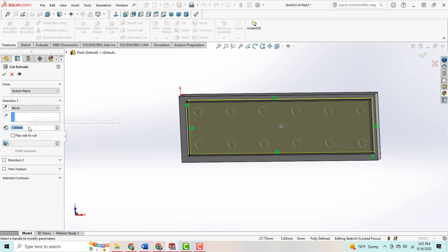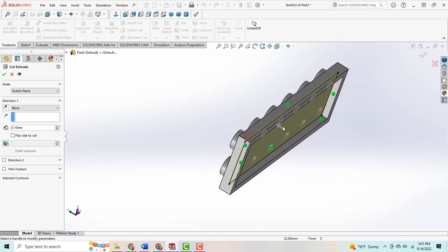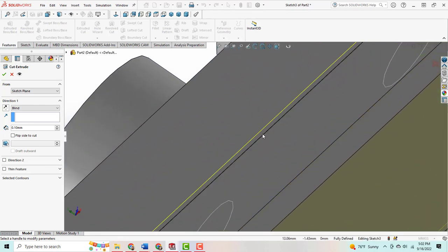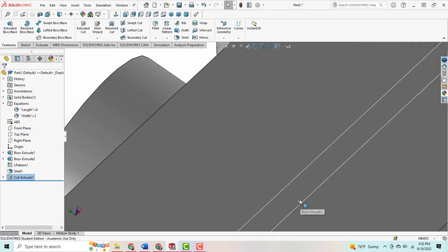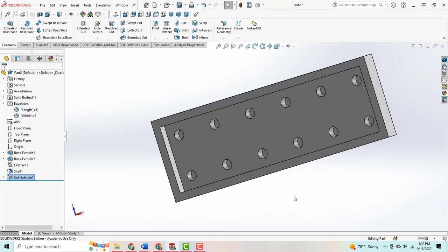and this depth is going to be 0.1. So it's going to be extremely hard to see. So make sure you rotate your model and you notice the direction with this arrowhead that the cut is being made. We want to make it inside of our Lego part so that we get that tiny bit of an extra little cut. And then hit OK. So you can't really see anything different being done, but it is there. We can see that on our Feature Tree Manager.